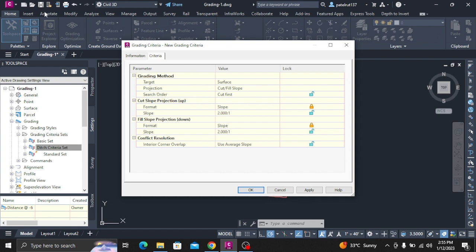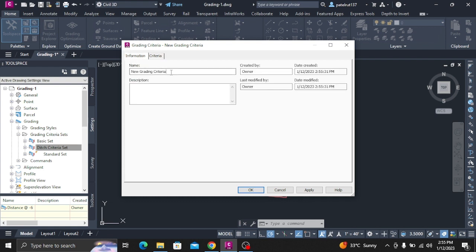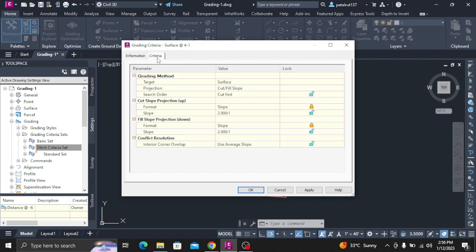The parameter table displays values for Component 2, which is the second slope pattern component from the left side. In this case, it is a long line with a tapered line symbol along the top of the slope. In the slope line symbol section, change the symbol type to none. For further exploration, for component 1, in the slope line section, change % of length to a higher value. You can see the results in the preview pane.